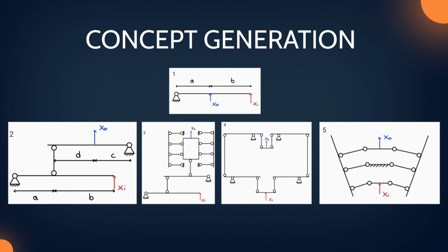The second is the double lever, which is similar to the first option but guarantees more compactness for the same demultiplication. The third option consists of adding a double compound to the second concept. This has the advantage of reducing vibration and maintaining rectilinearity, but adds a layer of complexity to the system, which reduces predictability and makes machining of the part harder.